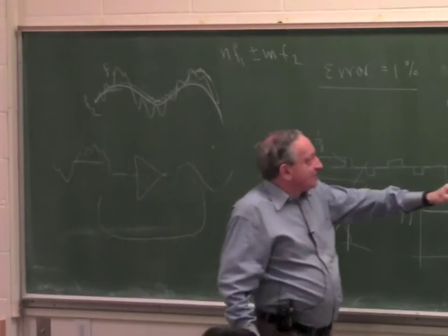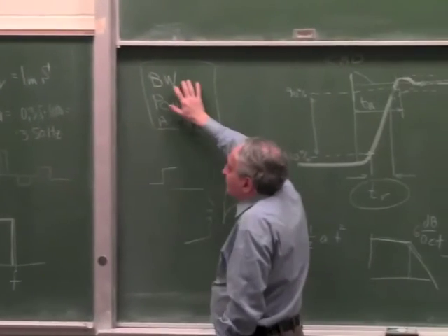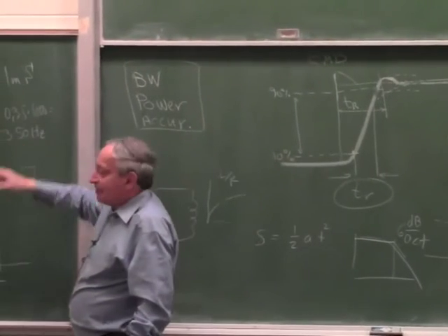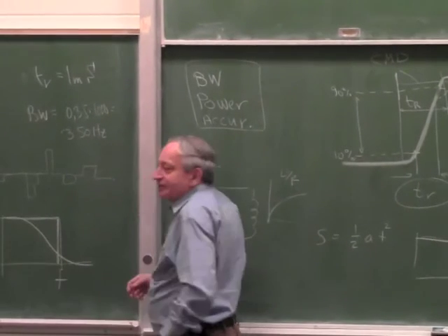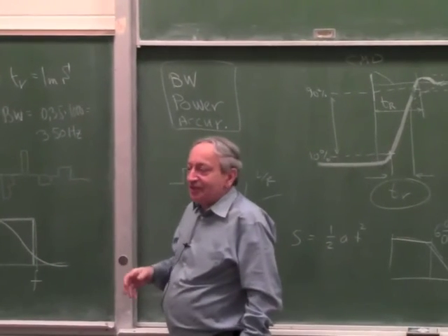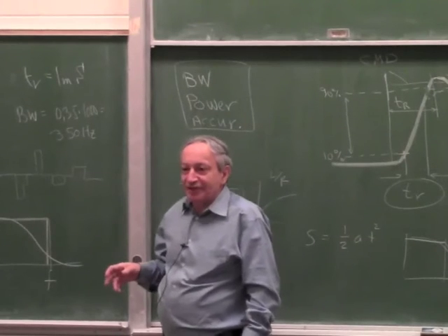So now back to this. Now we know what bandwidth the system needs. We know what filter to put, and it's never a sharp cutoff. It's always a nice, gentle filter. Either a simple RC or something which is called a raised cosine. It's a very popular filter in telecom.